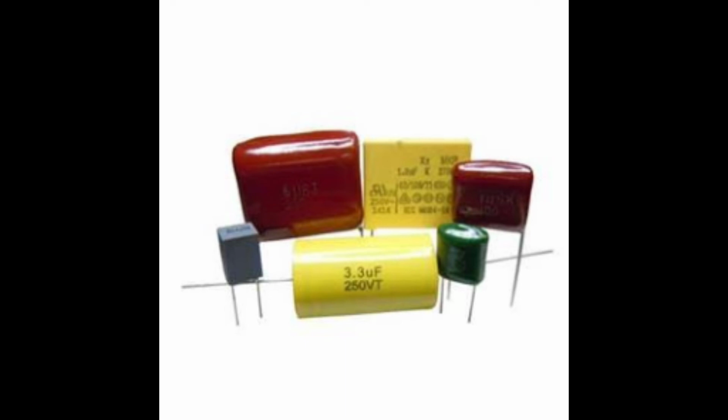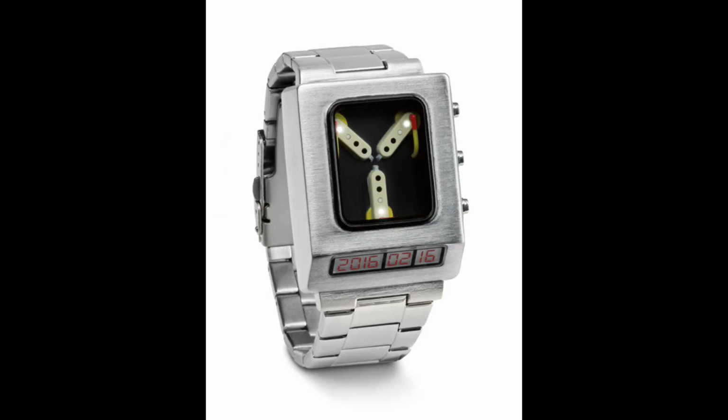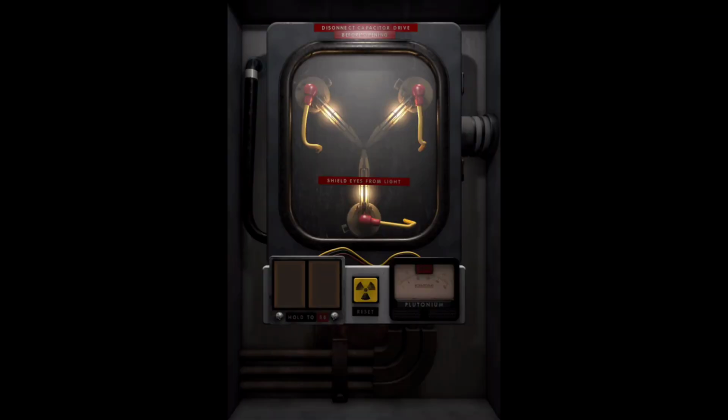Film capacitors use film, usually a plastic or sometimes paper, as a dielectric. Some applications of these types of capacitors include high power induction heating and low power applications such as sample and hold and VCO circuits. They are also used as AC motor run capacitors and power factor correction capacitors.